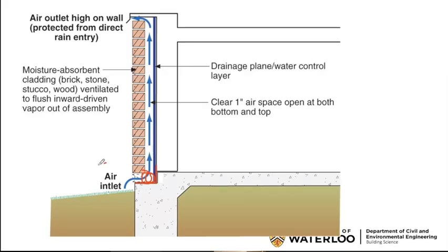at the bottom. So this air inlet at the bottom, and it's one reason why Max, the comment about a fibrous baffle. See, the problem with the fibrous baffle is it will actually significantly retard airflow. Doesn't mean we don't do it. Just telling you that that is an impact of putting too small of a weep hole or plugging the weep hole with insect screens. So you have to make your choices.